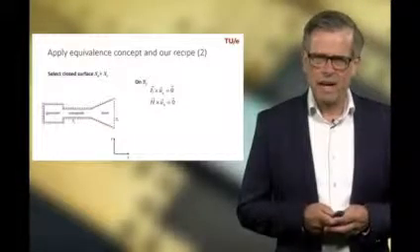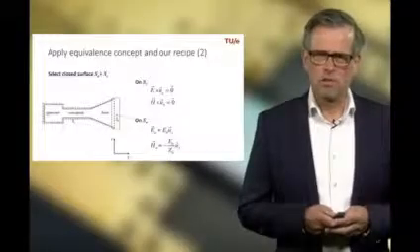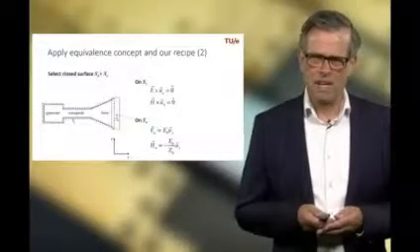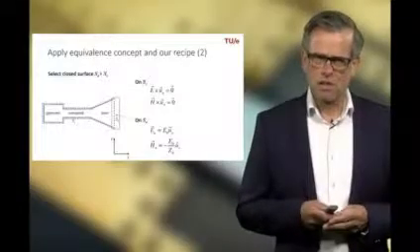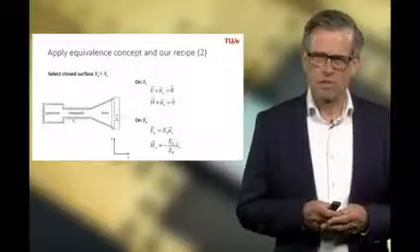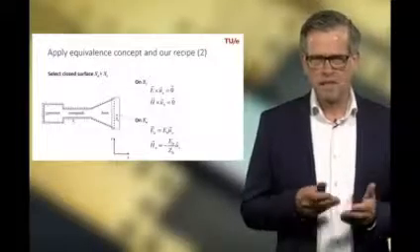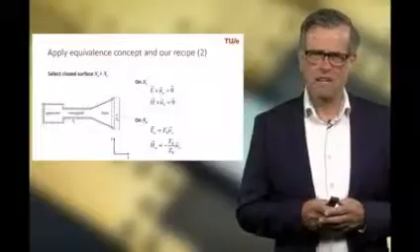On the radiating aperture, so on SA, we will assume that we have a uniform electric field distribution directed along the y-axis, and the corresponding H field is given here and is directed along the x-axis.